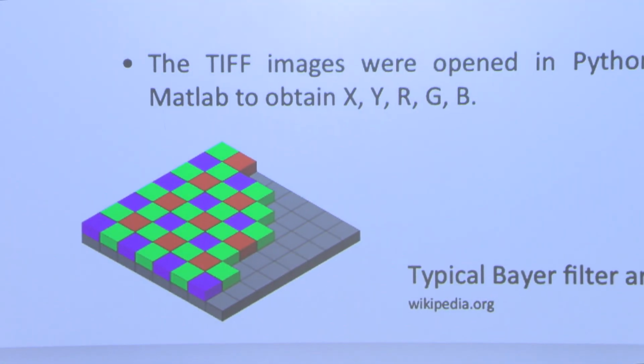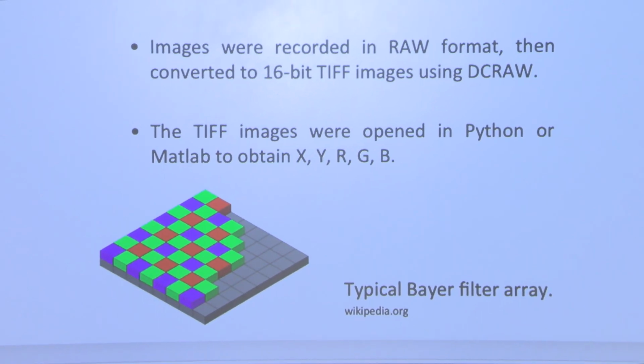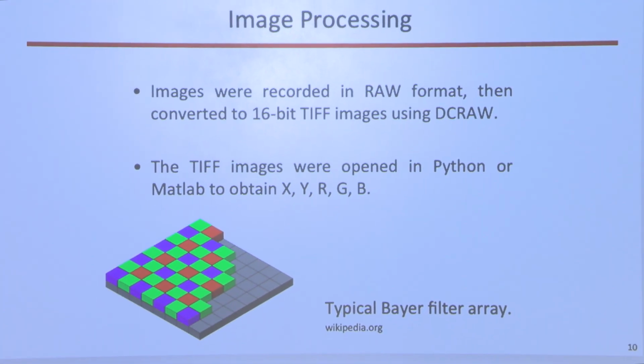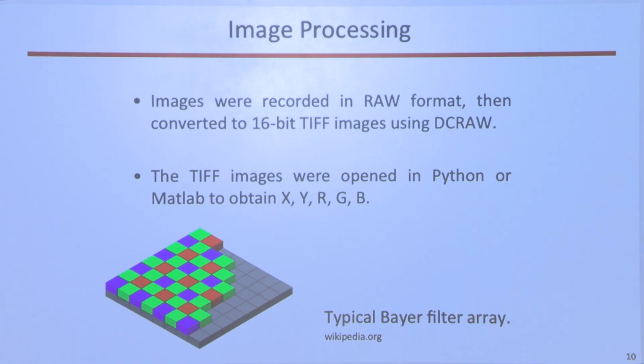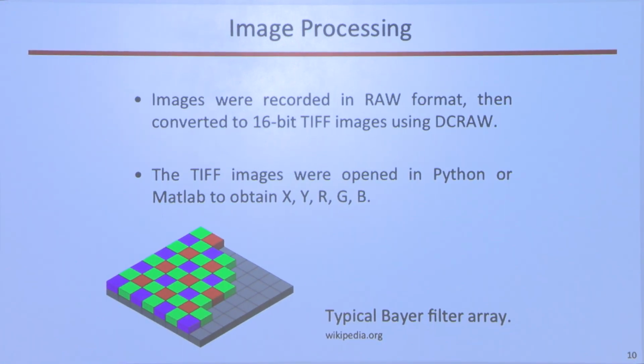And this image on the lower left here is called a Bayer filter mask. So what happens, whether it's a CMOS or a CCD camera, and all the cameras you have in your pockets on your cell phone, you may have 20 megapixels, and every pixel is going to have a little dot of paint on it, whether it's red, green, or blue. About half of the pixels are green, because our eyes are most responsive to the green of the sunlight. So about half the pixels are green, and then you have some red and blue pixels. And there's a lot of proprietary software in here. People have tried to back out and to understand for each camera, like the Sony camera, which pixel's green, which is red, and which is blue.